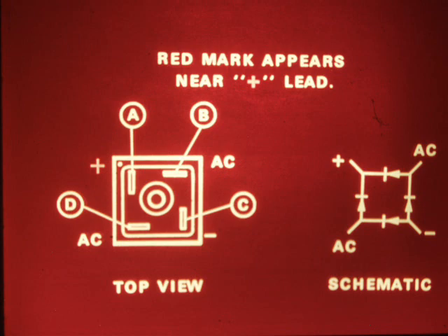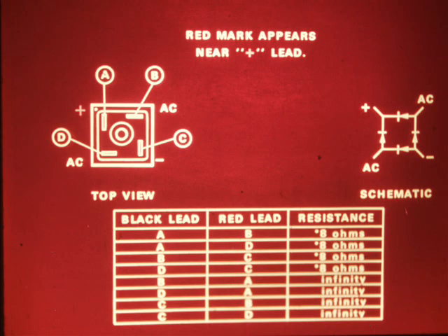The rectifier is basically 4 diodes which are connected to provide a DC voltage to excite the field. An open diode would cause a loss or reduction of field voltage. To test the rectifier, check each of the 4 diodes with an ohmmeter in both directions. There's a chart in the manual that indicates polarity and what the resistance should be.